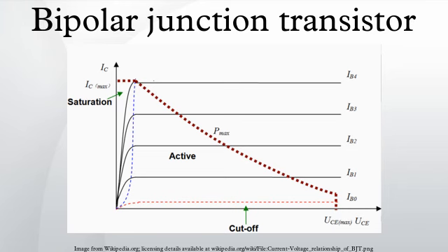Theory and modeling. Transistors can be thought of as two diodes sharing a common region that minority carriers can move through. A PNP BJT will function like two diodes that share an N-type cathode region, and the NPN like two diodes sharing a P-type anode region. Connecting two diodes with wires will not make a transistor, since minority carriers will not be able to get from one N junction to the other through the wire.